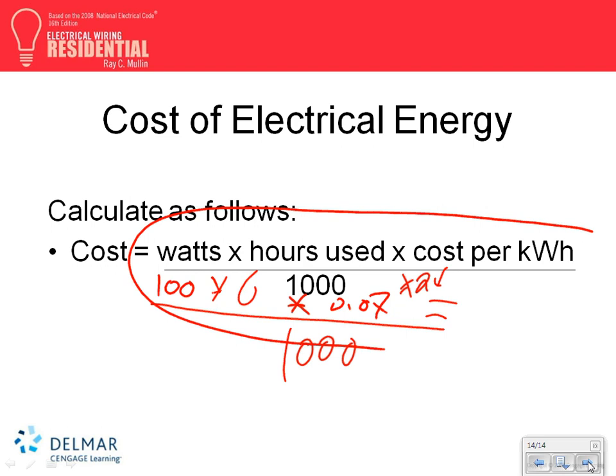Now, when you come over here, since there's 6, what do you do? First thing, you have to group them. So right in here, you provide a disconnect: 1, 2, 3, 4. These are the panels that the power's coming into. Look how they come over here, and then here's disconnect 1, disconnect 2, disconnect 3, disconnect 4, disconnect 5, disconnect 6.